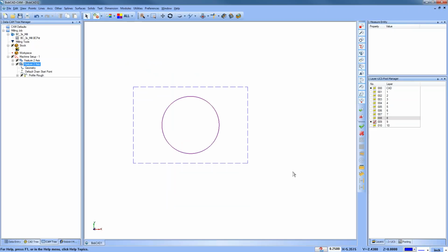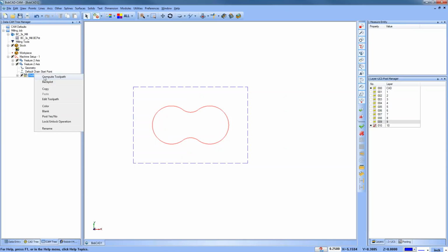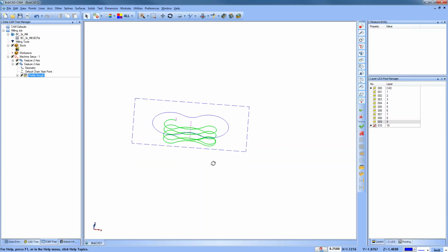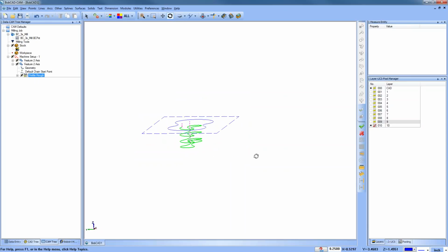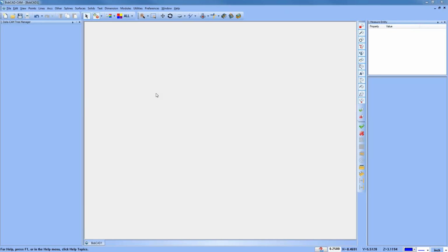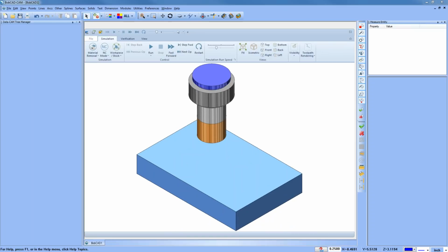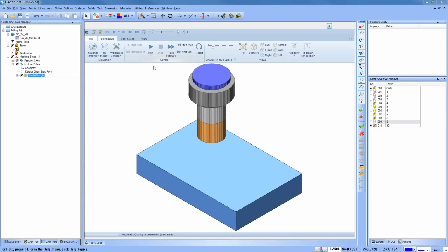Greater than the radius of the cutter is what you're looking at. And then the last one here, again, I just have an irregular shape. So I'll remove and reselect this shape here just to show you that the helical ramping is not limited to just circles. You could use this for a variety of different shapes. A lot of times it's a really easy way to remove material from the outside.